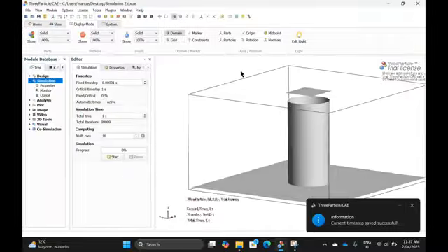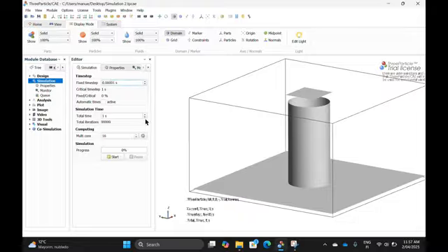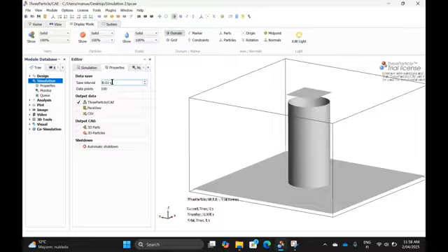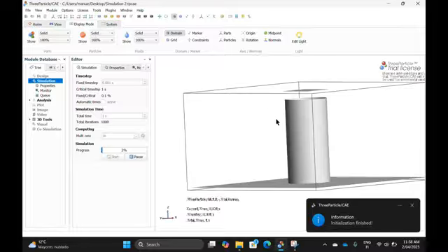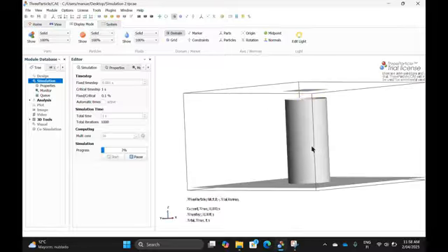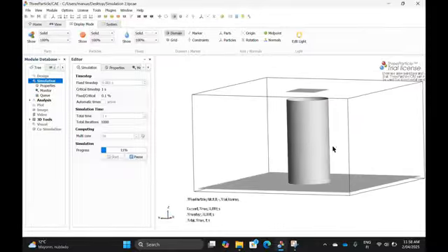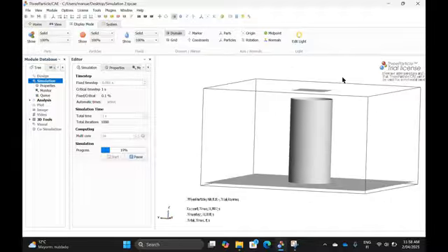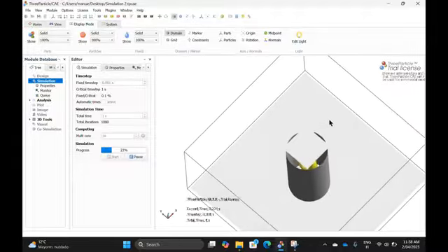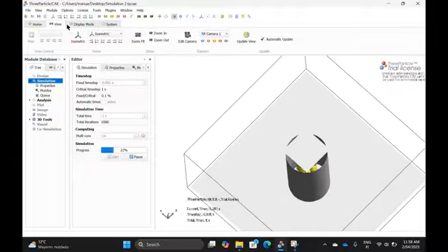Okay, now it's showing me this, this should be set default. Yes. Let's see. Okay, there is something that doesn't throw me an error, but no particles are coming into my system. Are particles coming into the simulation in your system? Yeah. From your plane? I will try changing it to a plane, okay? I don't know if the torus filled with particles, the donuts, works with that form of inlet.